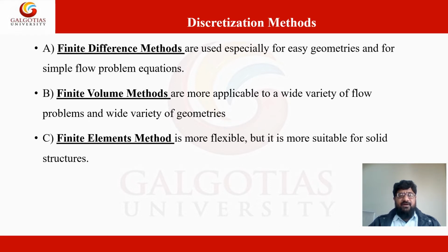The second one is the finite volume method, which is the most widely used, and it is at the heart of the commercial softwares, because it is applicable to a wide variety of flow problems and a wide variety of geometries. And the third is the finite element method. In the finite element method, we discretize the whole domain into elements, and the variation between the elements is considered. The finite element method is more flexible when it comes to complex geometry.